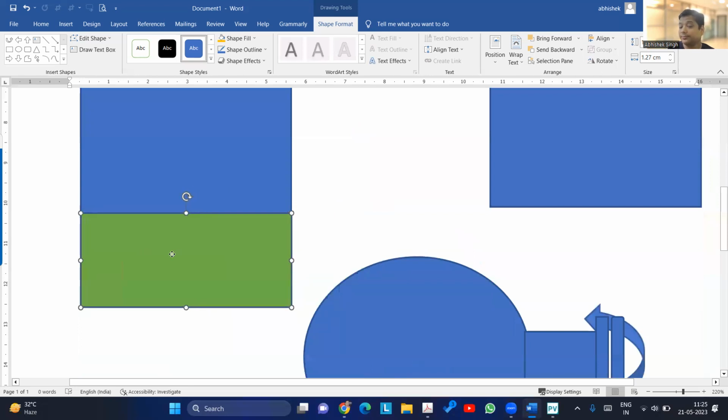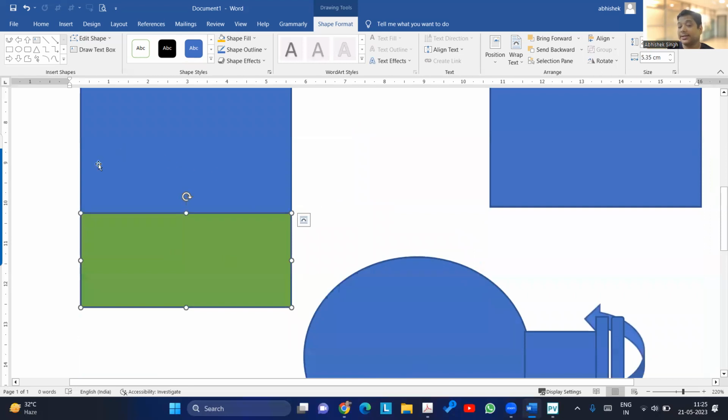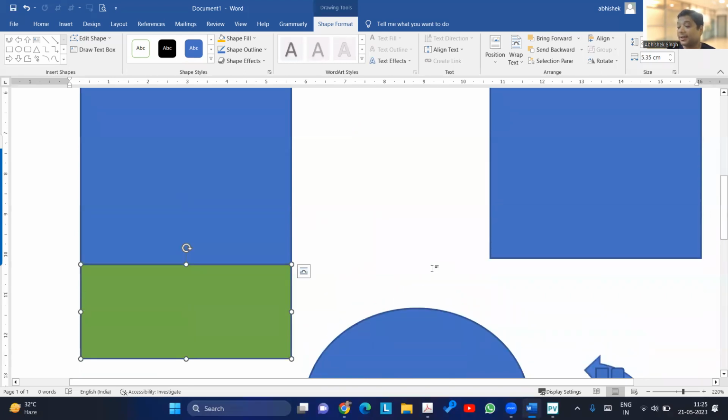For the support, you can balance the forces and find out the additional moment coming at the support location. And no, PV Elite does not take care of the nozzle neck. We have to perform an additional calculation for that.